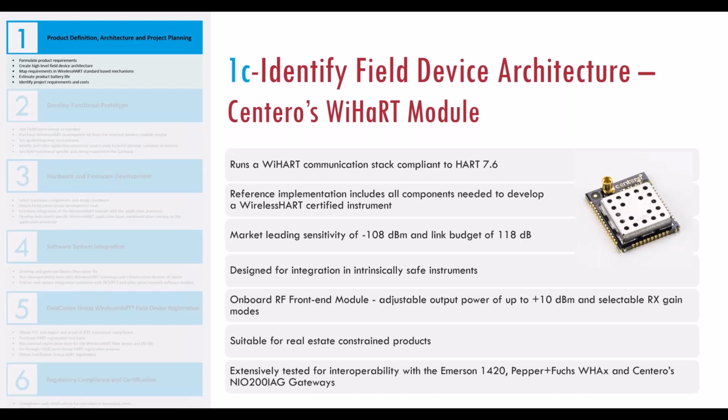Now, this helps a lot when deploying instruments out in the field, as it allows you to extend the connectivity between instruments and minimize the hop count. What I mean by that is, in a mesh network, ideally you would keep the depth of the mesh network as shallow as possible, because the more mesh layers you have, the more power the intermediate routers would have to eat up in order to route data on behalf of the devices that are positioned in the deeper layers.